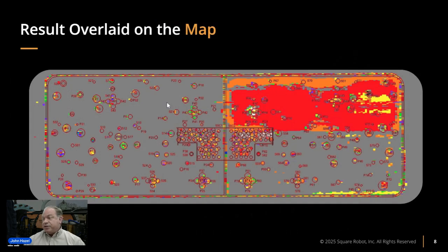This is a combination of those two. We've got the fabrication drawing plus the C-scan representation coming out of our system. And as you can see, everything is lined up, so our positioning system works very well. And the correlation for where there is an indication or discontinuity there. There are a couple of places where we do have a little bit of noise, but in each one of these areas, it would be followed up by looking at that. The analyst would look at that area specifically for confirmation.